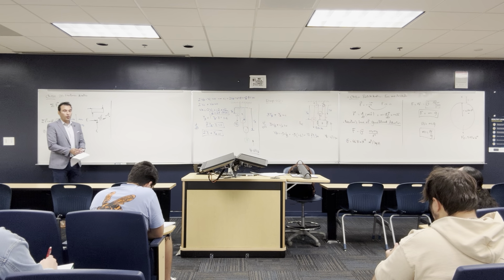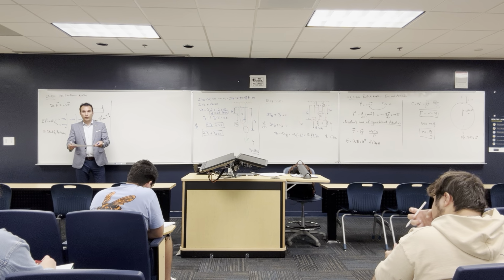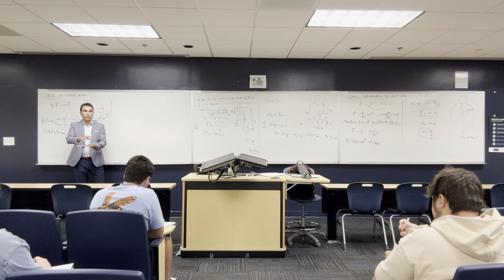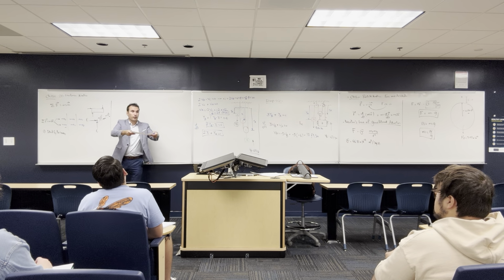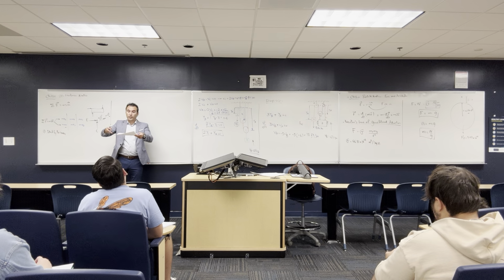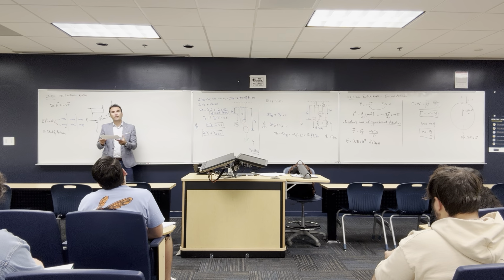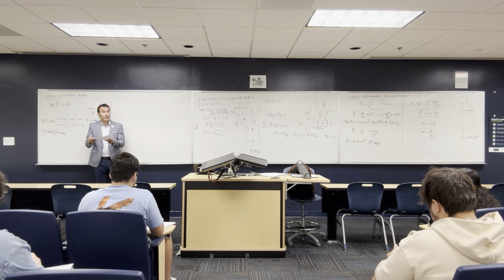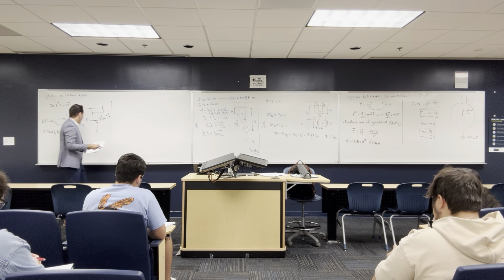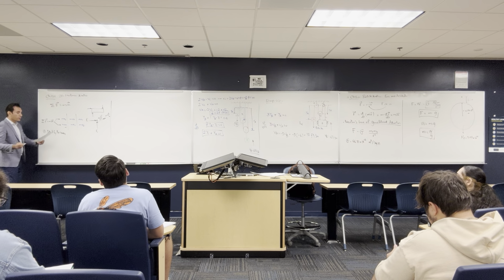Let's say you are shopping in Walmart or Target, and you throw something on the belt that is moving. You are studying this body, you are not studying the belt. That's why you have to identify the body, because the body is moving and the belt is moving, so which one am I studying? You are studying the body, so you have to take this body and isolate it and then identify all the forces on this body. So first, choose the body.